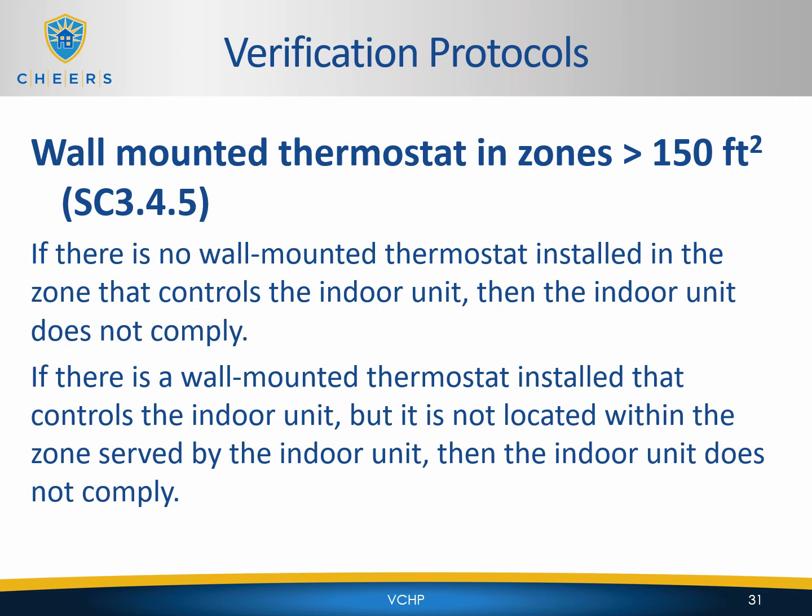If there is no wall-mounted thermostat installed in the zone that controls the indoor unit, then the indoor unit does not comply. If there is a wall-mounted thermostat installed that controls the indoor unit, but it is not located within the zone served by the indoor unit, then the indoor unit does not comply.